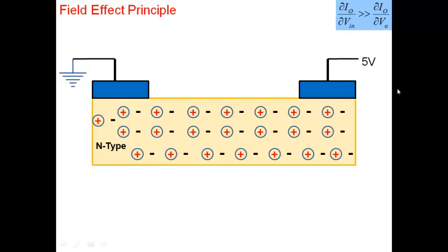It's a resistance. So if you plot the voltage versus the current, you will see a straight line. It obeys Ohm's law, V equals I times R, and R, as I said, depends on the doping, the thickness, the area, all of these factors that we are familiar with. Okay. Now let's suppose we do the following. We take another metal plate, and by some means, let's say you place it very close to the N-type semiconductor.